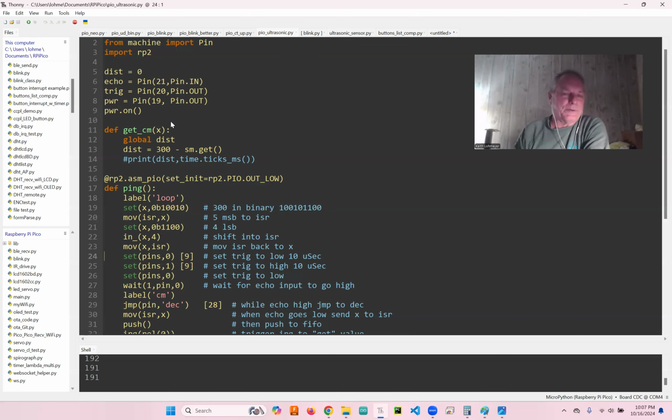But this is going to happen over and over again, and your interrupt handler just gets taken care of on a schedule. Your regular program's going to stop at a convenient point and go do this, and it's going to set the distance again. Next time you read your distance in your regular program, you're going to get whatever the latest amount is.